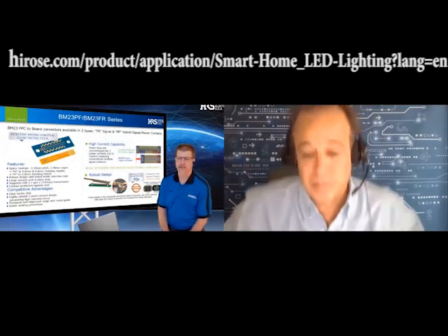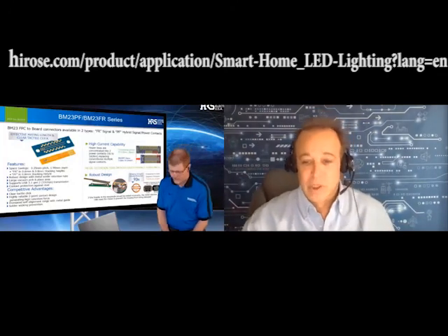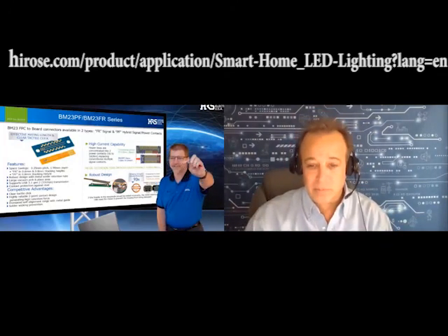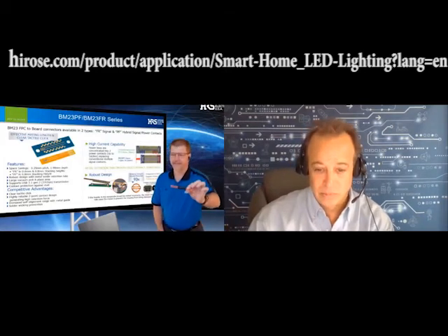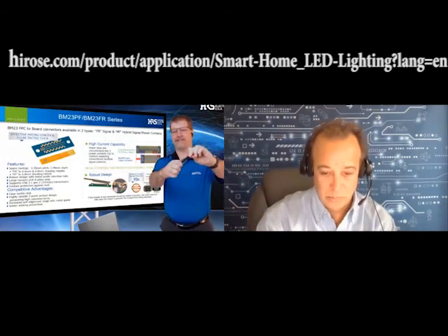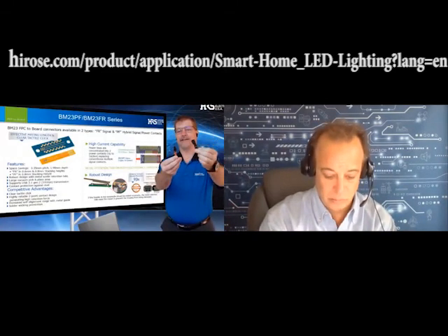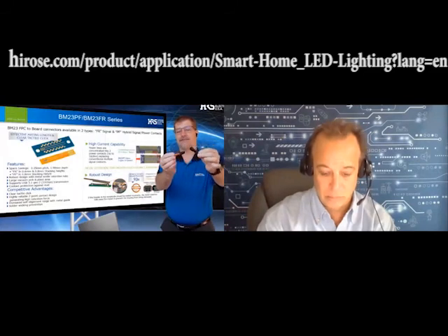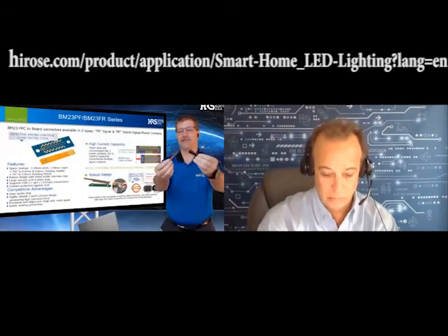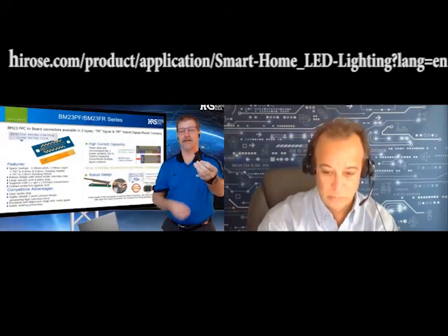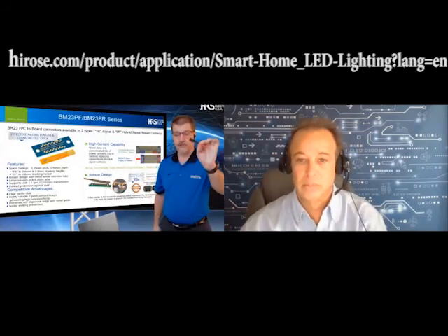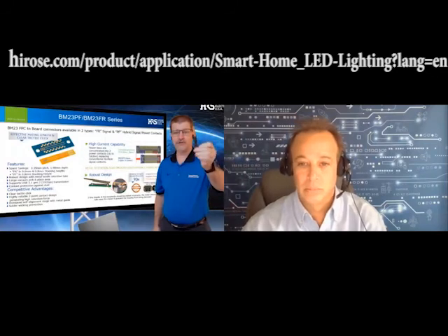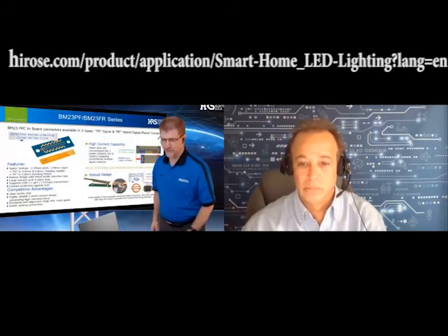LED lighting is a great application for us. We have lots of options. You're getting into smaller connectors, things maybe the size of this here. Sorry, David, but I have to show this. This is an inline connector used in LED lighting, with an IP67 rating. There's a gasket seal on the inside of the connector and even between the contacts. It's used in low voltage applications, typically a couple of amps. I have a couple of LED lighting customers using this outdoors in a truck mount type application. So it's a great little product for that.